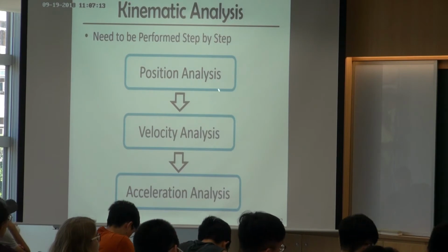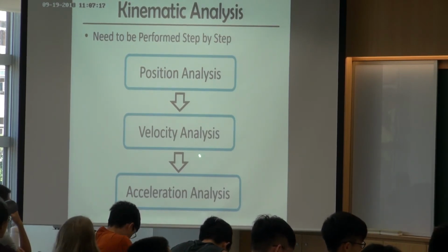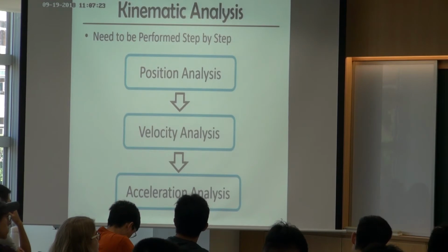You need to know the position first, then you can do the velocity. Then you know the velocity and position, then you can do the acceleration analysis. So you need to perform them step by step.